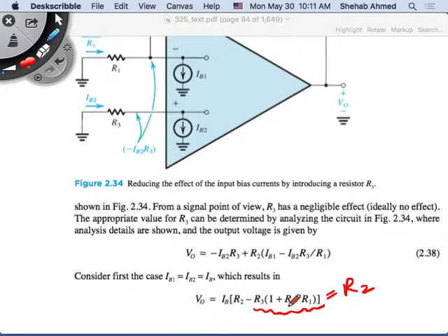So that means R1 has to be pretty big. Or I can just design R3 properly. Because you want to keep R1 and R2 independent, because you want to be able to control the gain of your amplifier, right? So one nice way to go around it would be to make R3 equal to R2 over 1 plus R2 over R1, right? That will cancel this effect completely, right? These two will cancel and they'll be left with R2 only. So then R2 minus R2 is 0 and then the output component is gone, right? So that's one way to go around it.